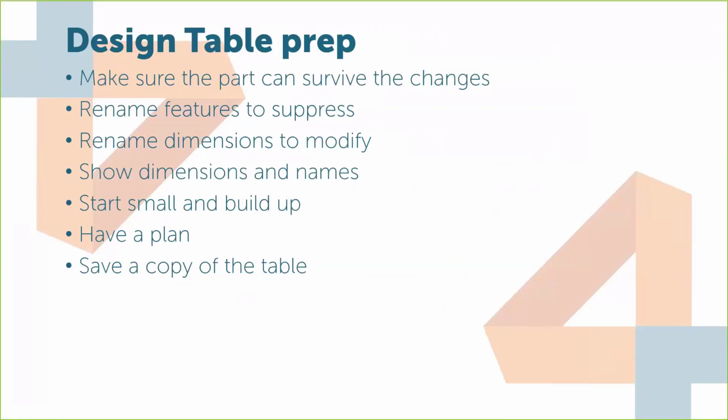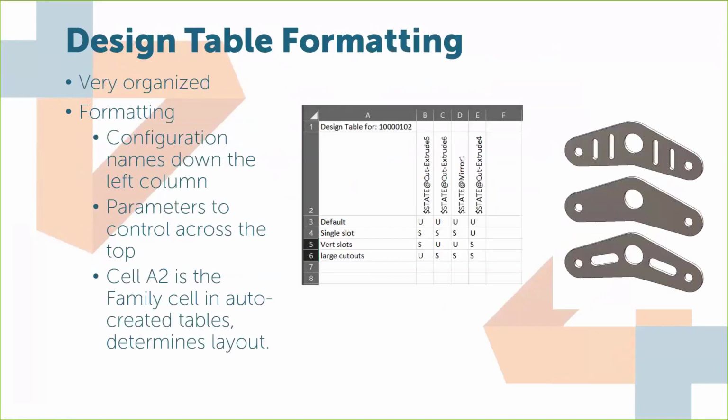And if anything happens to that Excel spreadsheet, because these are technically stored inside of our SOLIDWORKS models, if that design table becomes unable to open or something like that, that's not a good situation to be in. So you want to make sure that if you do get deep into design tables, and it's a very complex table, especially with formulas and maybe lookup tables and cross-references and concatenation functionality and all that, very powerful Excel functions, save that table, make a backup of it. If you use PDM, rev it in PDM just like anything else. It's just as important as the CAD data itself.